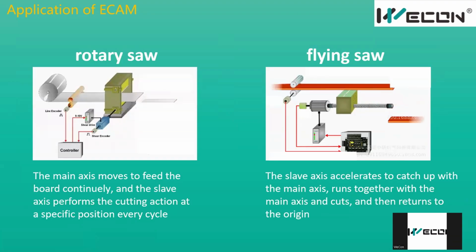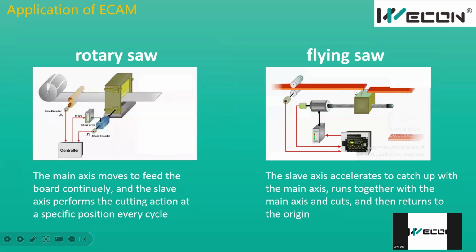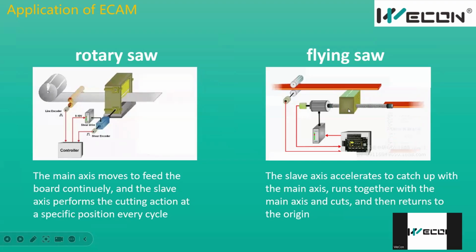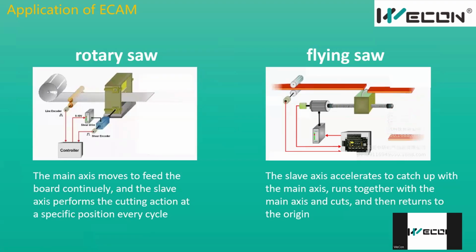First segment, the slave will speed up to catch the wood boards, and when the slave has the same speed as the wood, the cutter will go up to cut the wood and go down. And at last, this cutter will go back to the zero position and wait for the next cycle.